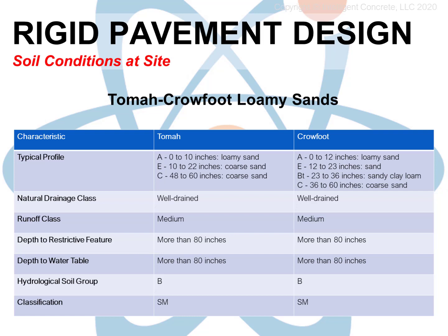Briefly, clean soil, that is, one that does not contain organics or debris, consists of coarse-grained materials such as rocks, sand, and gravel, and fine-grained materials such as silt and clay. Silts and clays are both very fine-grained, like dust. Coarse-grained soils are inherently stable. Fine-grained soils are less so, and in many cases are completely unsuitable for construction without significant modification.